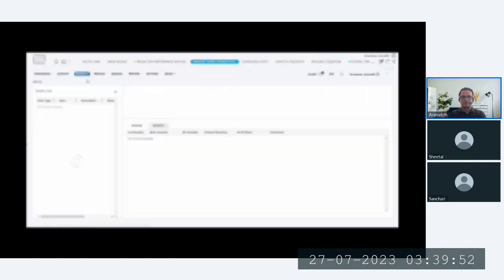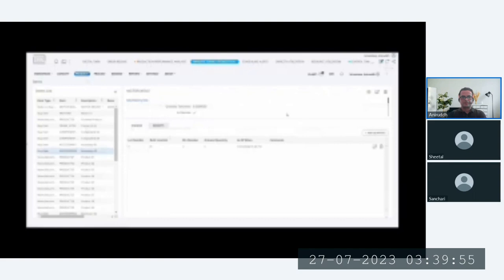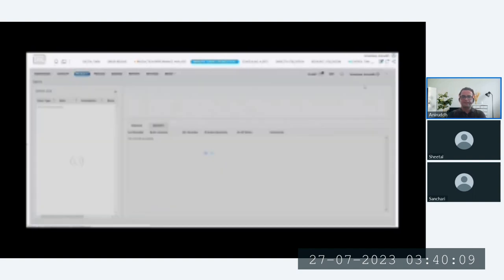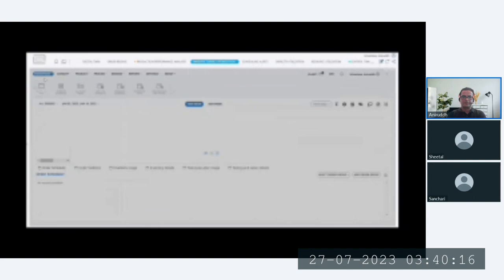Currently, the job has been scheduled, but it's been given this light greenish color because accessory 3 is not a critical constraint. It's a soft constraint, not a hard constraint. So let's see how I can change something like this. Going back to product, we select this item here, select accessory 3, and we edit accessory 3. As you can see, these are the different settings for accessory 3. We make this is critical, yes. We save it. We come back to the workspaces, and to see its impact, we will again generate a schedule with firm production orders and changeover optimization to see its impact on what is happening.